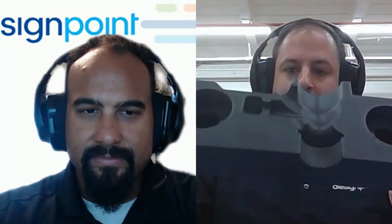Sure. So I print mostly in the material that I was just showing you. It's called Onyx. The generic name is carbon-filled nylon. And what I really like about this material is the surface finish. I mean, you get great surface finish. You get really good accuracy because nylon is a great 3D printable material. It has great layer adhesion, but this nylon has carbon in it. And the carbon gives you other properties, and those are resistance to UV light. It gives it higher strength. It gives it good resistance to chemicals.